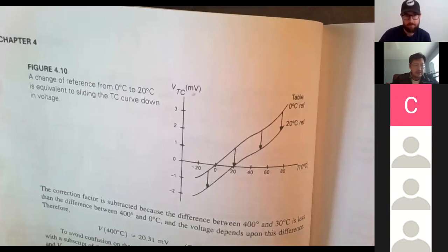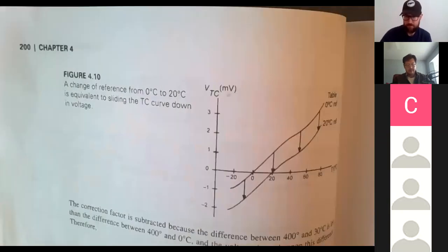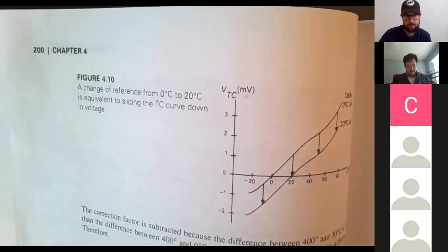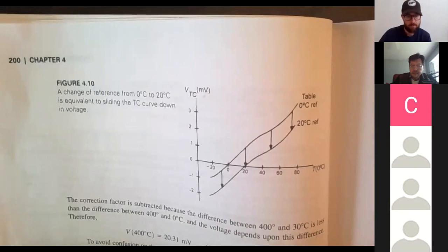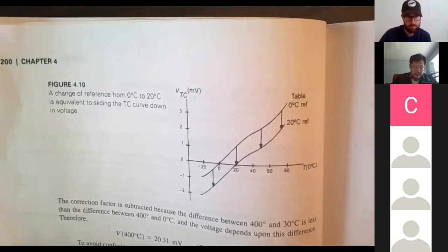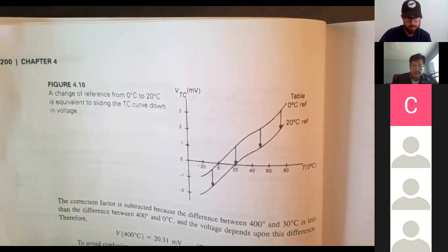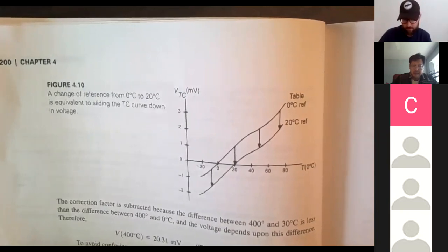They do have some fancy wireless ones, but you can't monitor them in real time. You have to extract them and then plug them in, and so ours are hardwired through the wall of the retort, and you can watch the temperatures in real time. And what they're looking for is cold spots in the can. If something doesn't cook all the way through, you'd have a cold spot in a section that's not cooked, and so it's not safe. And so every food that gets on the shelf has to go through these tests to make sure that it's being cooked properly.